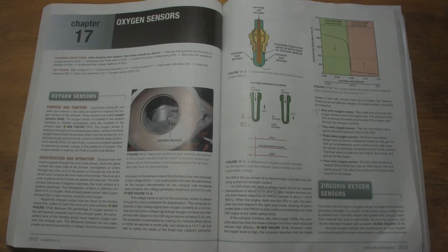So the computer is going to reference upstream oxygen sensor data in order to trim out and try to achieve your stoichiometric air-fuel ratio of 14.7 to 1, or possibly a little bit leaner under a cruise situation with low power. And then when we go to full throttle, we go into a mode that's called power enrich with a narrowband. It's a little bit different than the wideband, and we'll talk about that in the next chapter.